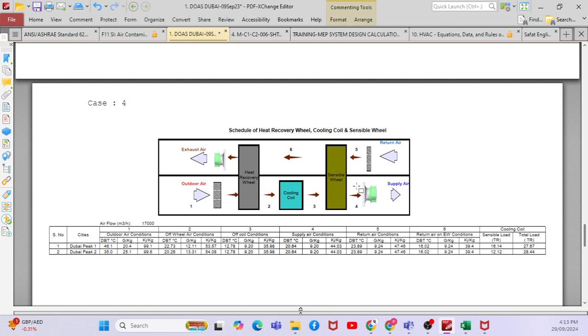So say for example, based on the delta T, 12 degrees and 24 degrees, what is the delta T? 12 degrees. To increase by 12 degrees, if I calculate the sensible load using the equation, it may give you around 20 kilowatt. We will see that in the duct heater portion, why the duct heater or heater is required, clear?